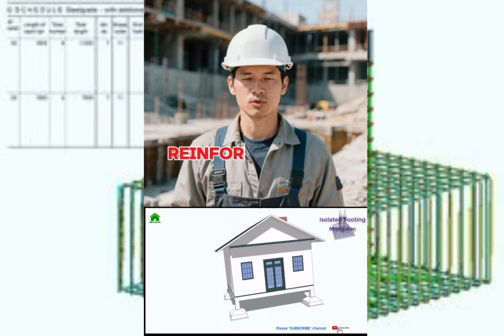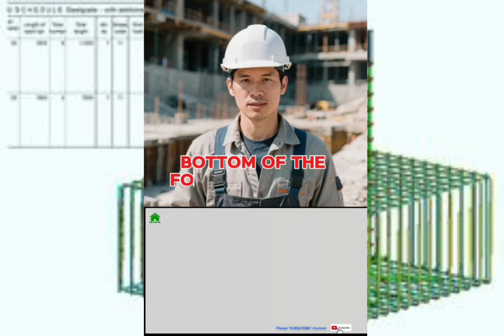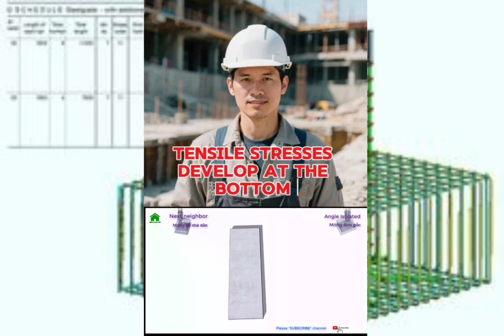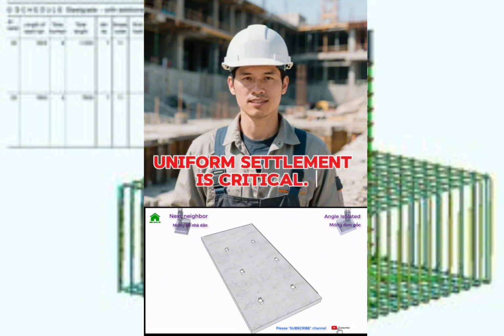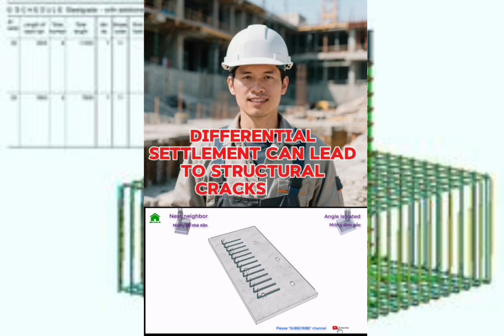4. Reinforcement design. Reinforcement is typically placed at the bottom of the footing because tensile stresses develop at the bottom due to upward soil pressure. 5. Settlement control. Uniform settlement is critical. Differential settlement can lead to structural cracks and instability.